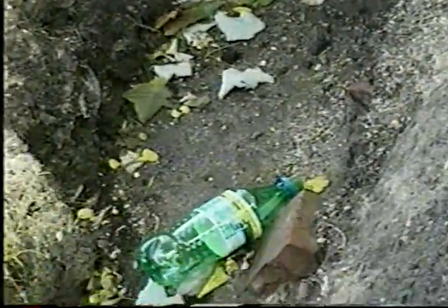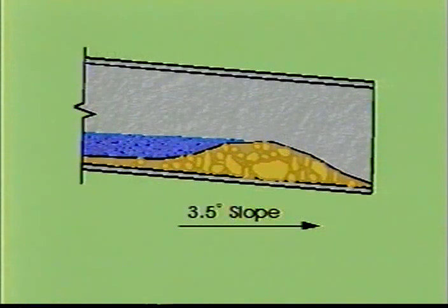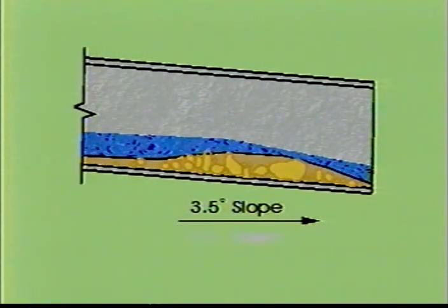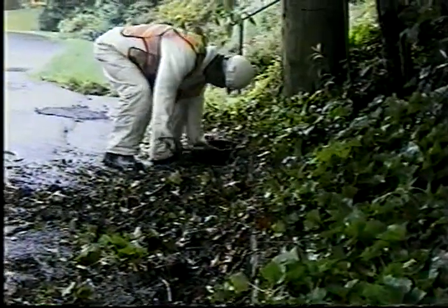Culverts may become clogged if the flow line grade prevents self-cleaning. A permanent correction is to relay the pipe on a steeper grade, but this is not always possible. The alternative is to clean the pipe frequently.